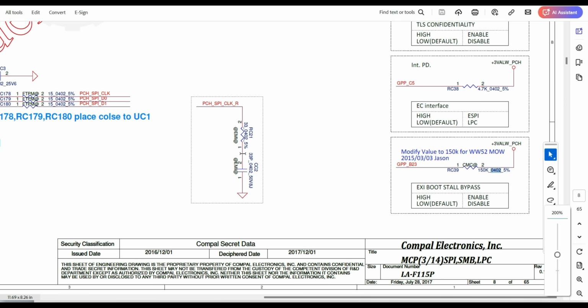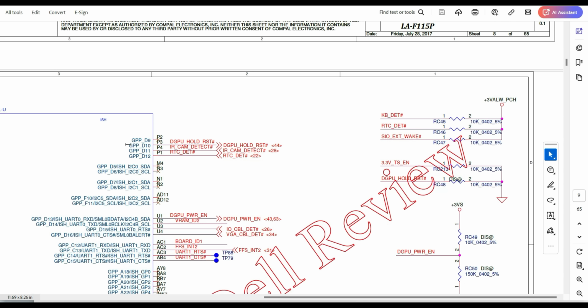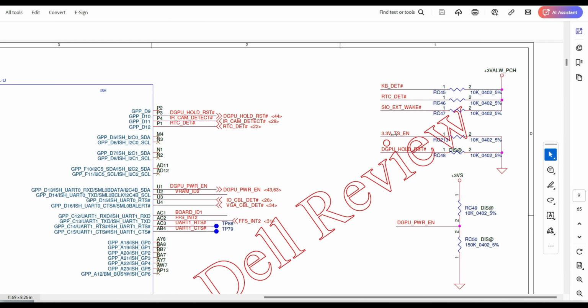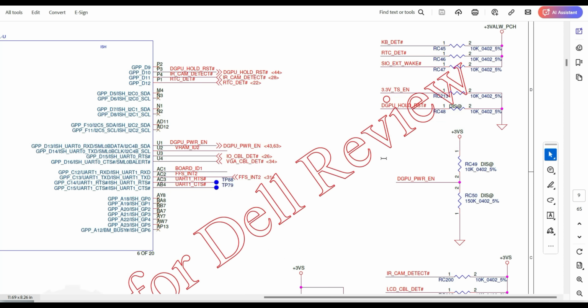Okay, here is the pull down, but here it's connected to the capacitor. Here is the pull up. See, wherever you get the line with the logic, it may be 0 or this voltage or lesser than this voltage. Here is 3 volts; here maybe 3 volts or may not be. Okay, in case of this line, here 100% it's 3 volts, and here it's ground, 100% ground.